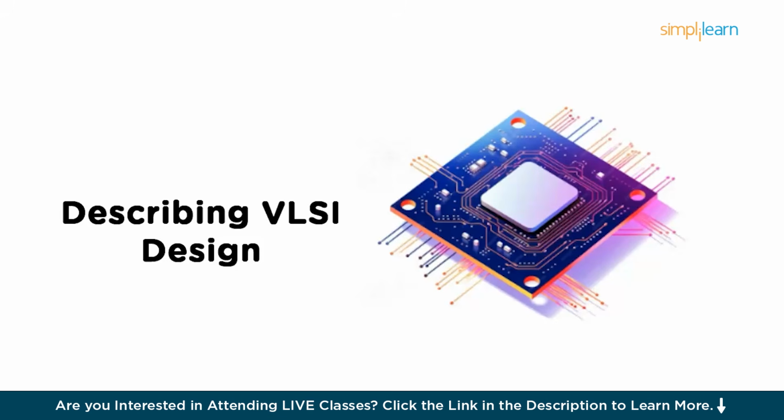So in the field of VLSI, very large scale integration design, engineers face the challenge of creating highly complex, efficient and reliable integrated circuits (ICs). The development of these ICs requires both precise design methodologies and tools that allow for accurate descriptions, simulations and verification. So this module will explore three key aspects of VLSI design. The first one is describing chips, the Verilog part, then testing designs virtually, the simulation part, and quick prototyping with FPGAs. Each of these topics is integral to the process of developing, testing, and finalizing the VLSI design.